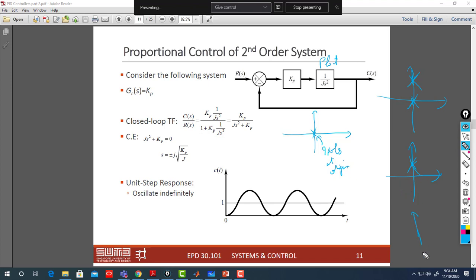However, if you have two distinct poles at the imaginary axis of your second order system, this is a marginally stable system, as you said. But in this case the system is unstable.